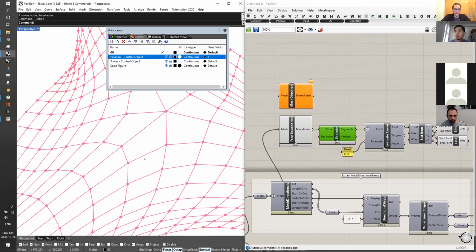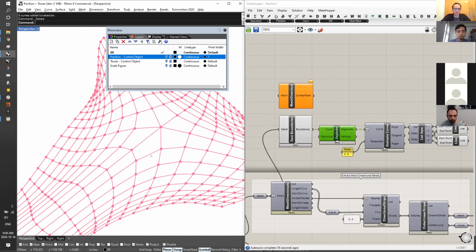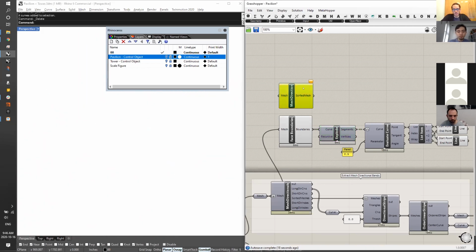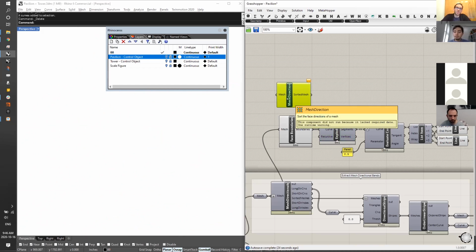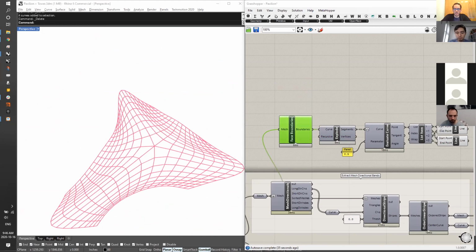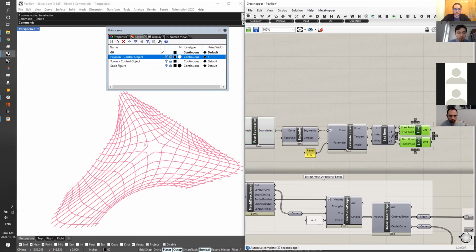So they're all going 0, 1, 2, 3, 0, 1, 2, 3, and so forth. This component by Daniel Piker will do a lot of that work for you, but there's a chance you won't get 100% directionals. That's purely based on the way the mesh is constructed, and it ties back to the idea of clean modeling. If your mesh is very clean and well modeled, you should always get consistent, clean directionals no matter what.